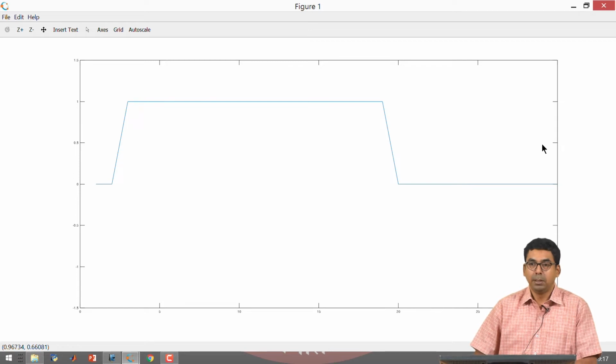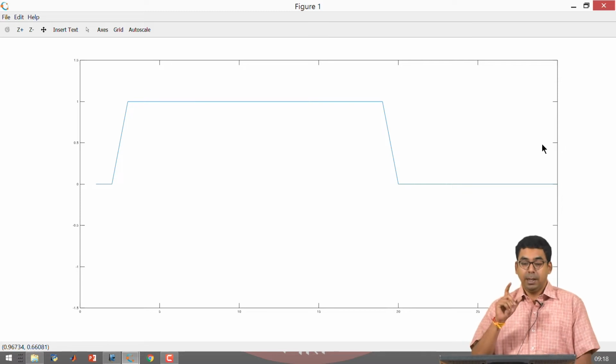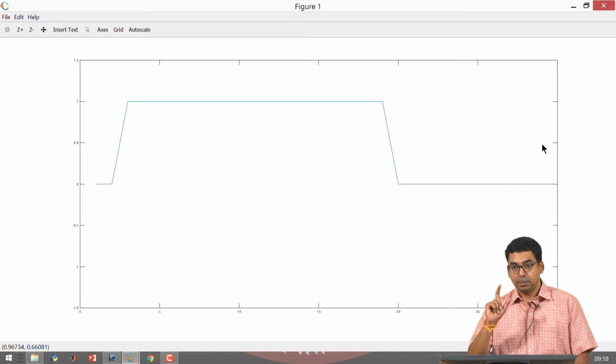You had a forward voltage of 1 volt. On the right hand side end, what could have happened is there was a reflection, and the reflection has to be understood in more detail. It didn't just reflect 1 volt, it actually flipped the 1 volt in sign and sent it back as a backward wave, and you had a superposition of 1 volt traveling forward and minus 1 volt going in the backward direction, and the superposition was actually 0.